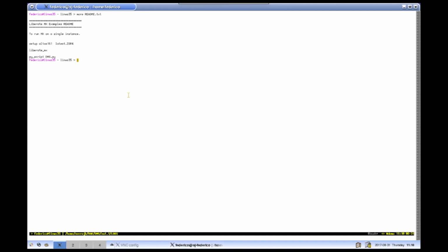All these operations are contained in a Python script, and that can be run through Liberate MX through this simple command. To give you an idea of what this script contains, it is a very basic set of commands to load the library, find a match for the specific arc we are interested in, and then print some information about what was obtained, what the specific lookup tables contain, and how to access that information.